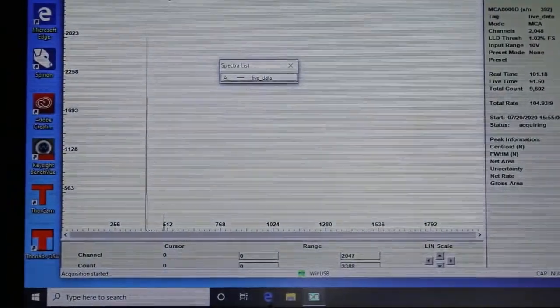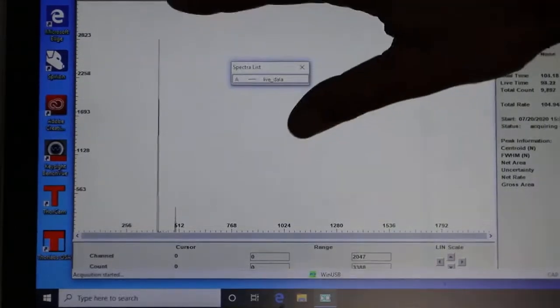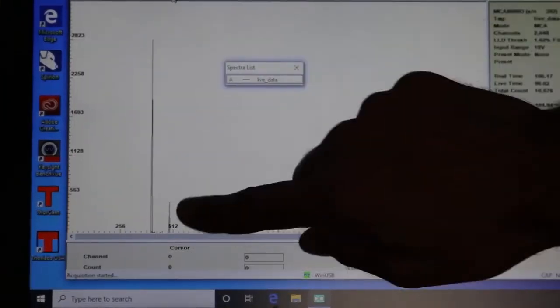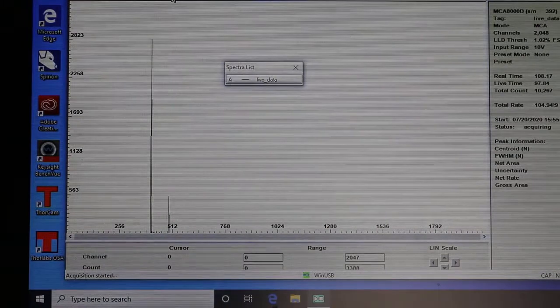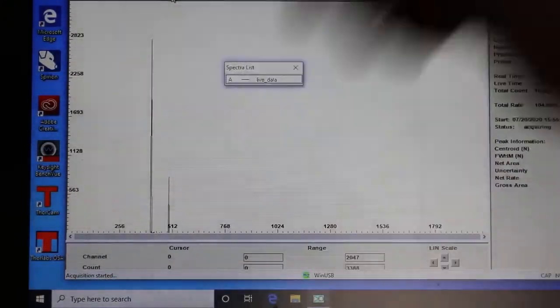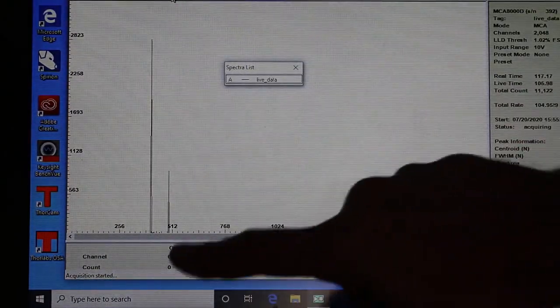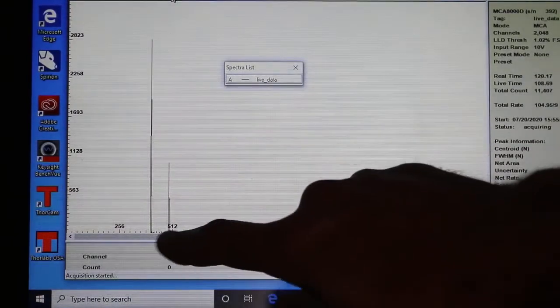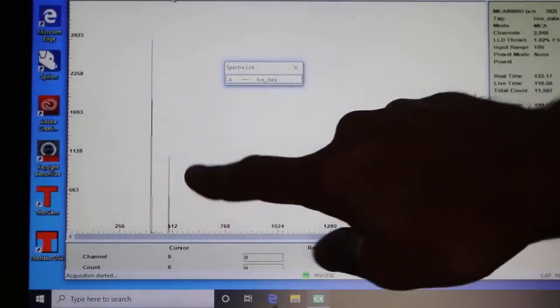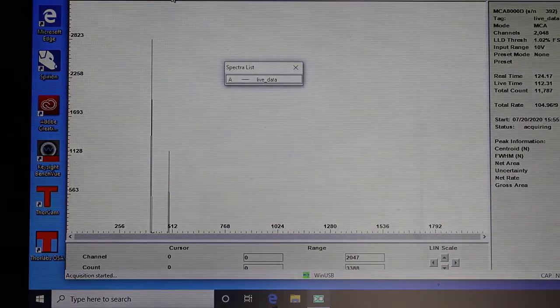When I do that, I no longer see this original peak growing, but one right next to it is starting to grow. Why is that? Well, the voltage is larger now. So the multi-channel analyzer is mapping the larger voltage into a slightly larger channel. This larger voltage has been seen about 1,100 times now, and off it goes. The peaks are very narrow because, plus or minus some sampling uncertainty, it's all more or less the same voltage, so we just see these spikes.